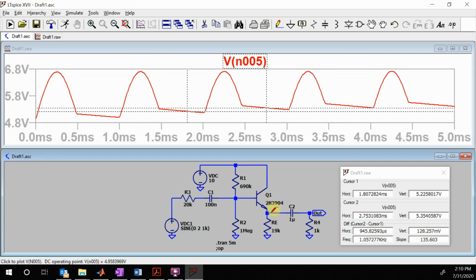So in saturation, we can only have 0.2 volts across here. So is this within 0.2 volts of 10? No, we're only at 7. That's good. And then does this point approach ground? No, everything looks good. So it's not a voltage clipping problem. So we've got to figure out what's going on. Well, okay, so let's look at current.